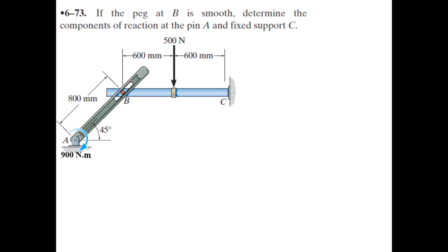As you can see here, this structure is a mechanical structure because it is supporting the external load. But this is very different from the truss structure that we solved just now. So if it is not a truss structure, then it can be a frame structure or a machine structure. So we have to identify which one this structure is.